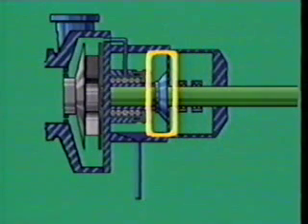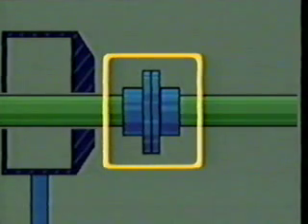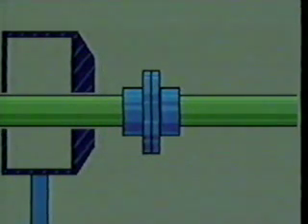Right here, next to the bearing housing, are flinger rings, or shields. They're attached to the pump shaft and fling fluid leakage from the packing gland away from the pump shaft. That keeps the fluid from leaking into the bearings. You already know that on most centrifugal pumps, couplings join the shafts of the driver and the pump. They have to be flexible enough to handle misalignments between the shafts, as well as changes in the driver's speed.